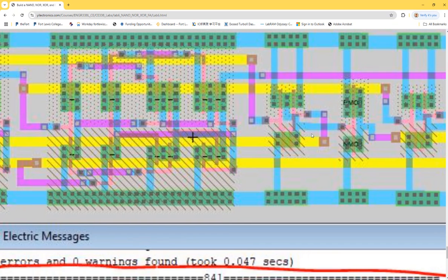This happens in so many different places. You can see the examples like this. You can see from here is the gate, right? So the circuit design requires this pink layer to be shorted to this place for some reason. I don't know, but you know. And you see that right after this poly layer gets out of the transistors' dense area over here, whenever I have a space, which is not against the design rules, for example, it has a required spacing, okay, I directly drill a hole to metal 1 and connect to metal 1.